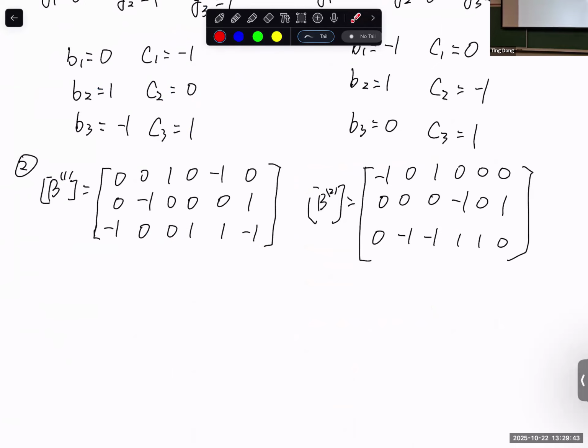And we know the K matrix has B transpose times C times B. The C matrix purely depends on the Young's modulus and Poisson ratio, so let's plug in those two values. For the C matrix, we don't need to differentiate element 1 and element 2 because it's the same. As long as elements 1 and 2 use the same material, the C matrix should be the same.